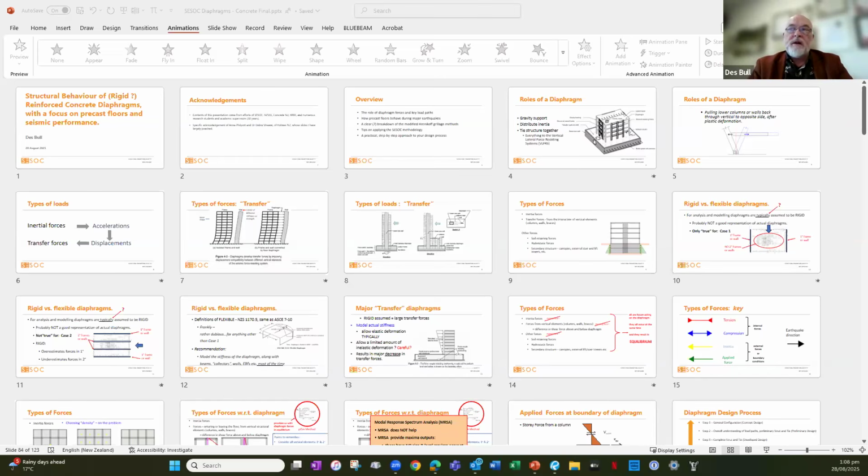Line up with what, in terms of the two points? Center of mass in the middle and wide apart is usually a good recommendation. What we've also done in the past is one of those dummy nodes is fixed in all directions, and the other one is allowed to roll in the direction of the earthquake. So there's actually no restraint. But if you pick a low enough stiffness in the dummy nodes, just to complete the mathematics, you can have them fixed on very soft springs for all directions, and it should be fine.